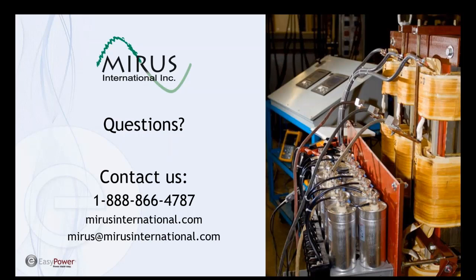We have a few questions all around the same topic, so I'll just group them into one, asking about efficiencies of our filter and of passive filters in general, how efficient they are, and how that would affect the overall efficiency of the system. There are some variances in the efficiency of different types of filters. I can tell you that our input filter is greater than 99% efficient, so there's only 1% losses introduced by the filter. The larger filters are actually much better than that even, so you get to like 0.5% in losses. So we introduce very low losses into the system.